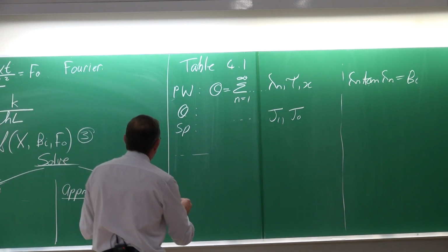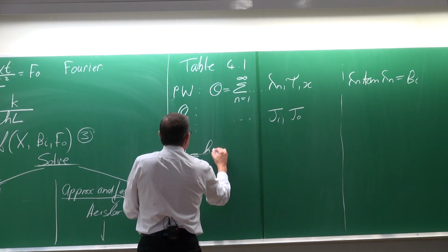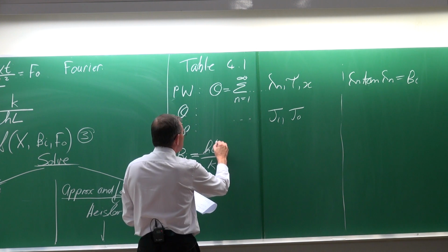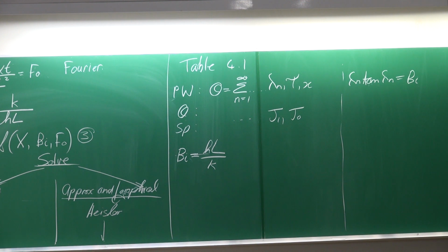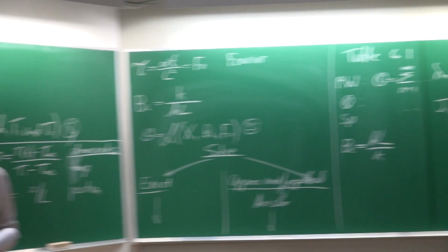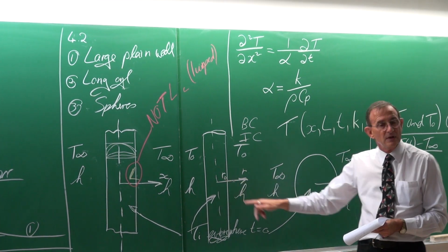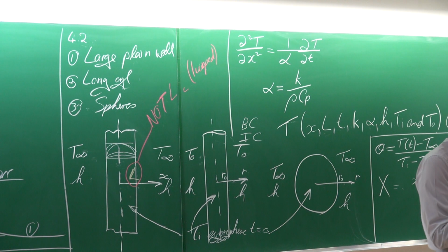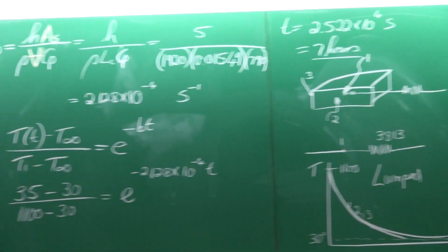It defines, for example, the Biot number. The Biot number should be calculated as hL divided by k, and it specifically mentions there that the L should be the characteristic length, this one, and not the one of the lump system, while for the cylinder it would typically be r0, and for the sphere it will also be r0. So it's very specific about it. Also in it, I'm going to read it to you. You need to highlight that in your textbook, if I can give you advice.